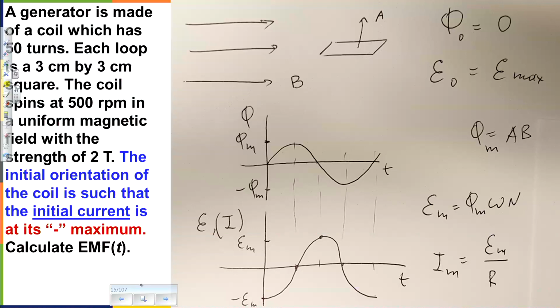I just said trial and check. You only have two options to choose from. One option has a name counterclockwise, second option has a name clockwise. So for this option, flux would become negative. That is wrong because the graph says the flux is supposed to be positive.